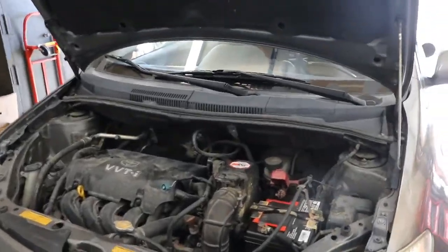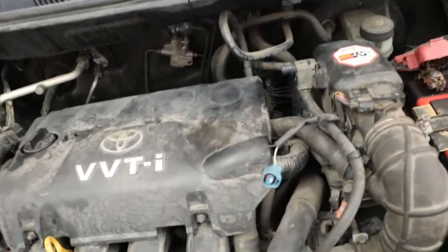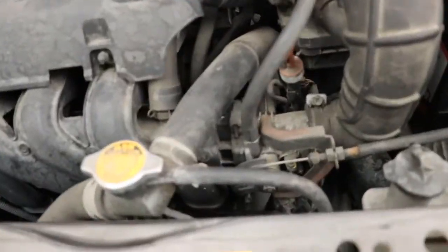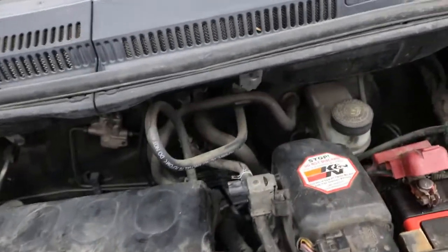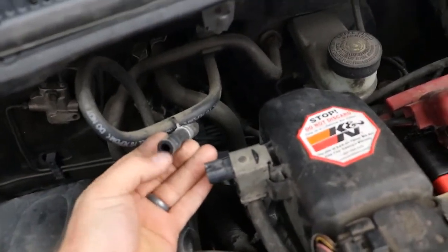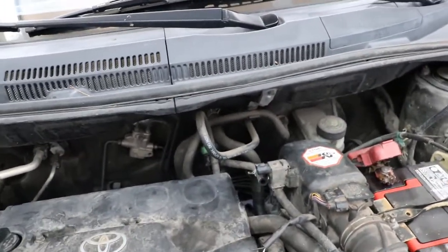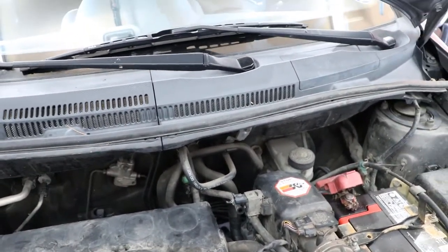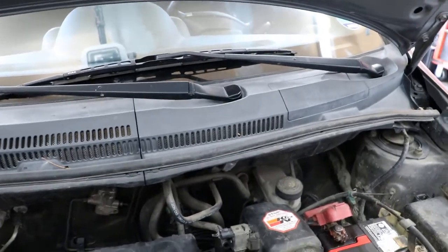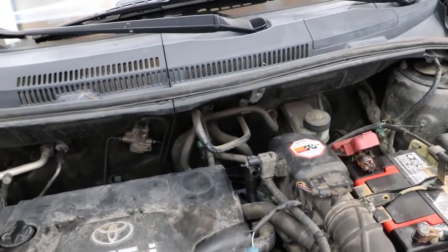Alright guys, so now that we figured out the purge valve is working great, the connector is broken, it seems to be a major problem, and we may have a small leak from this front hose, I'm going to go ahead and do a next test, which is to see if the valve is open in the back or if it's leaking. I'm going to keep it open for right now, and then I'm going to manually close it from my scan tool, and then I'm going to try to perform a light vacuum test or a pressure test on the system here.